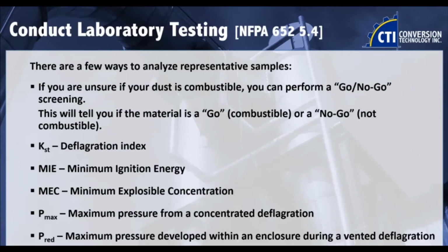So KST is the deflagration index, or how explosive your dust is. So something with a KST of 12 is technically a combustible dust because it has a KST value, but that is very low versus certain flours, which are 250. There's a huge difference. The PMAX is the maximum pressure from a concentrated deflagration. So those are the two that get tested together after your go, no-go saying, yes, this is combustible, and how combustible is it?